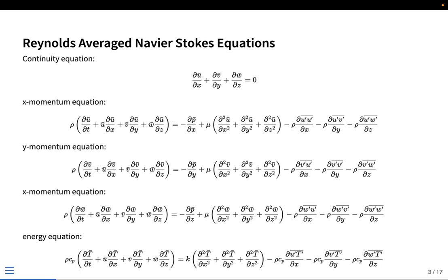So these are the equations describing the Navier-Stokes equations for turbulent flow. Again, we are assuming several things. So this is the time averaged equations. These terms can actually be zero in the normal RANS formulations because we are averaging over time. These terms will actually turn out to be zero, and we'll be left with the steady state equations alone. But we have written them in a general form called unsteady RANS.